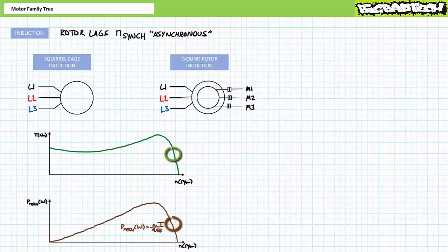If you were to concentrate on the far right side of the speed, torque, and power curves at and around the rated conditions, the plots should make intuitive sense. Load an induction motor up and it'll slow down. Unload the motor and it'll speed up. I know it's not really linear, and there's a clear roll-off as the motor approaches breakdown torque and maximum power, but if you squint your eyes just right, at or around the rated conditions, performance is relatively linear. In addition to experiencing peak efficiency in this region, it's largely for this reason motors are ideally operated at or near the rated condition. Load the motor up, it'll slow down. Unload the motor, it'll speed up.